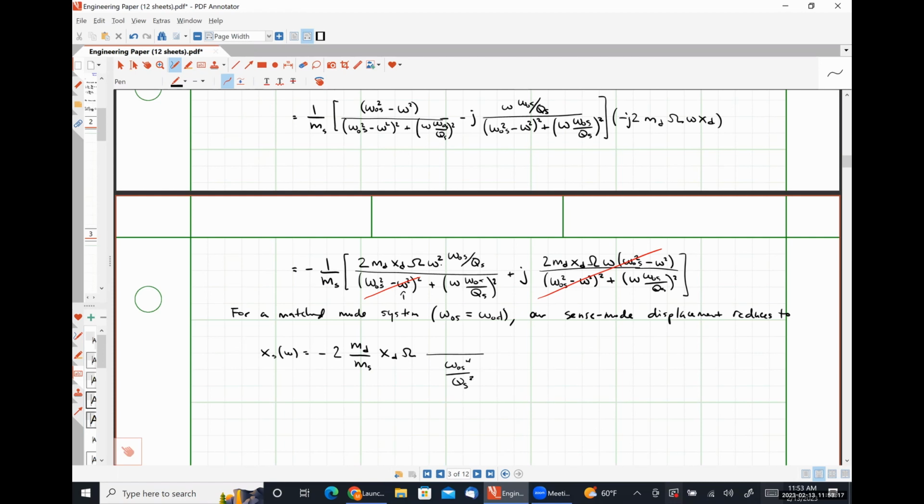And then up here in the numerator, we have omega naught S squared times omega naught S, which looks like omega naught S to the 3rd power over a single QS, right? So this QS cancels out one of the powers here. This omega naught to the 3rd cancels out this guy here. And that whole thing reduces to QS over omega naught S.